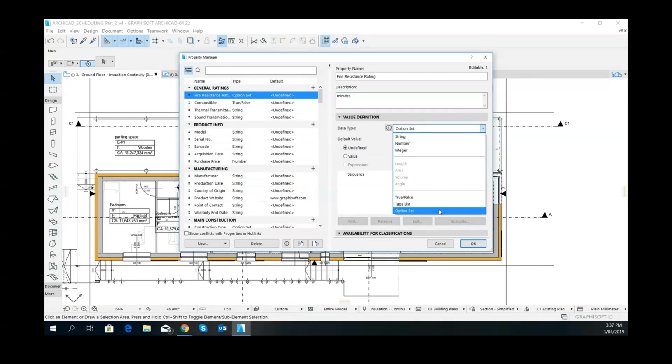Sometimes you're showing stuff on the plan, like furniture, and you could have an in contract option. If it's in contract, you make it true. If it's out of the contract, you make it false. So that later on, when you create schedules of furniture and fittings, you can find just the furniture that's involved in the contract rather than all of the furniture you've placed there to make it look okay.